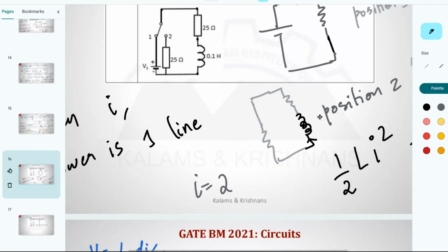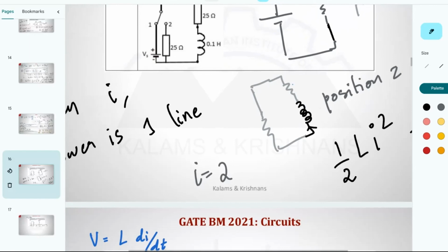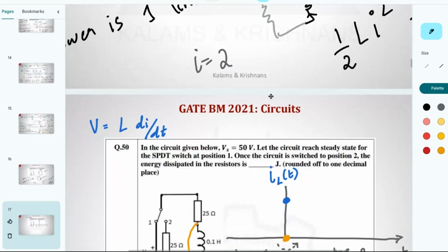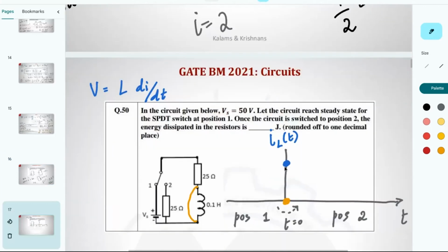So there is that can drive current here. That can take care of expenses. Eventually, that gets lost, right? So notice what happens to this current as a function of time. It's an LR circuit. It kind of exponentially decays. This is just an L over R circuit. The decay happens at tau equal to L over R.